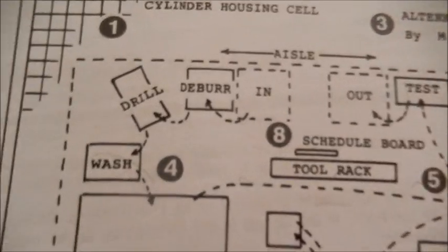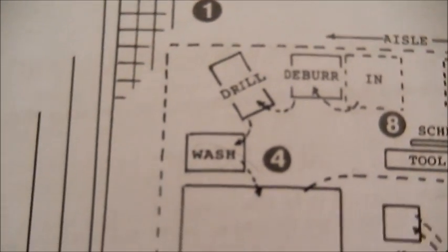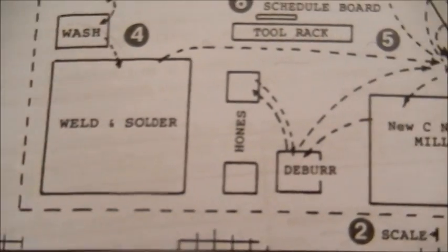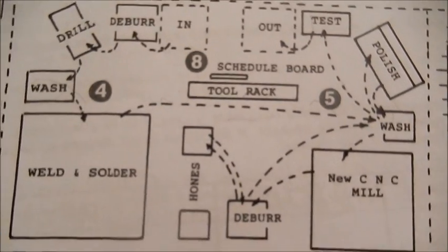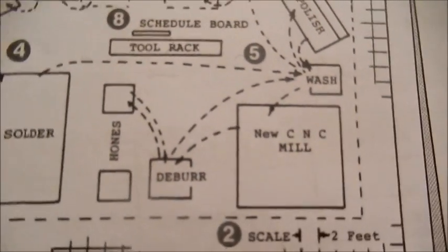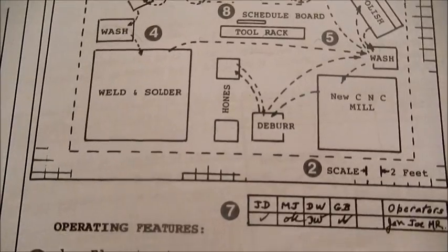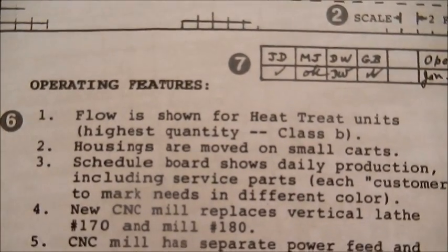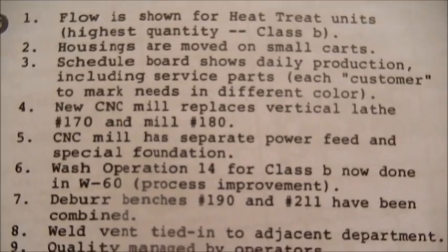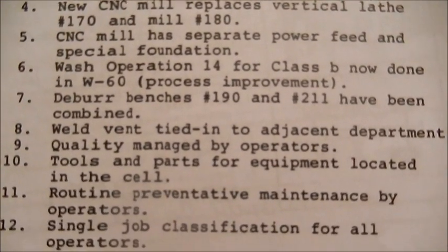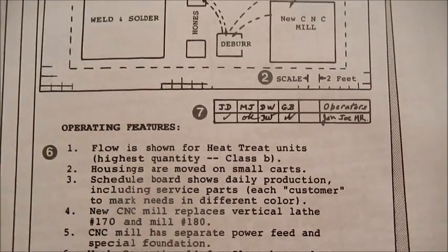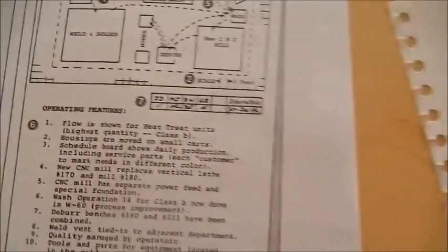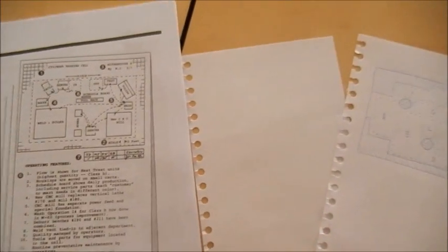Then, following the equipment and flow diagram made in the previous step, we have to place and draw representations of machines and equipment in particular shapes. Next step is to indicate the flows, at least for the dominant class of parts. Then it is important to indicate and write down how the parts will be moved or handled from one operation to the next. Also, we have to make references about the operations, and in the end it is useful to have several alternative cell plans because each plan has different features, benefits, costs, or risks.